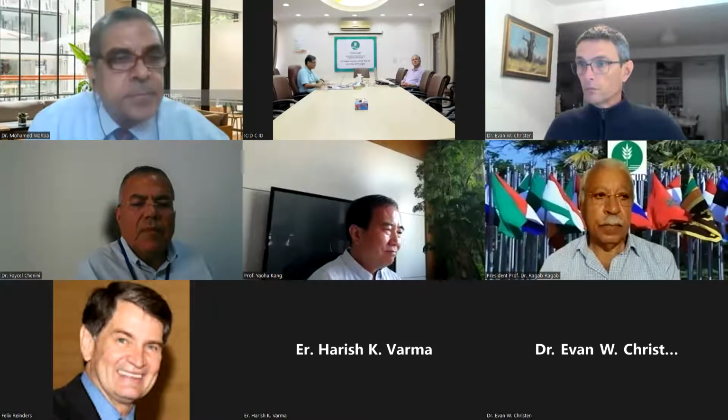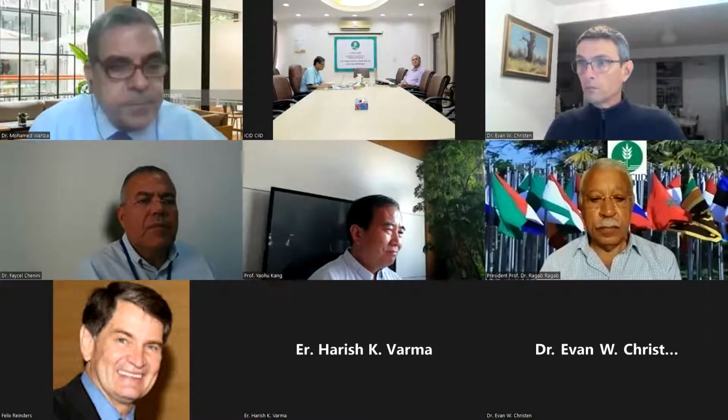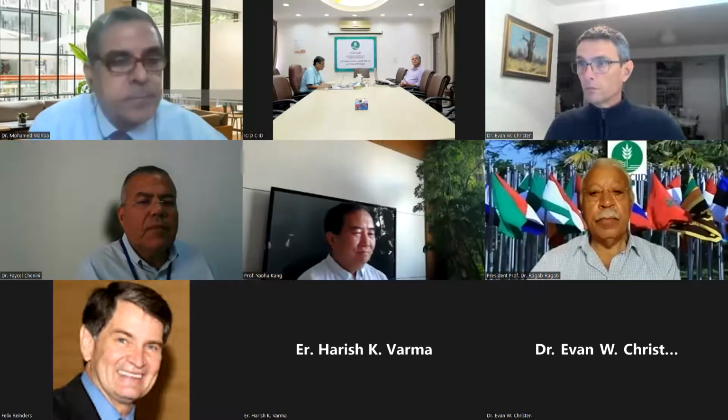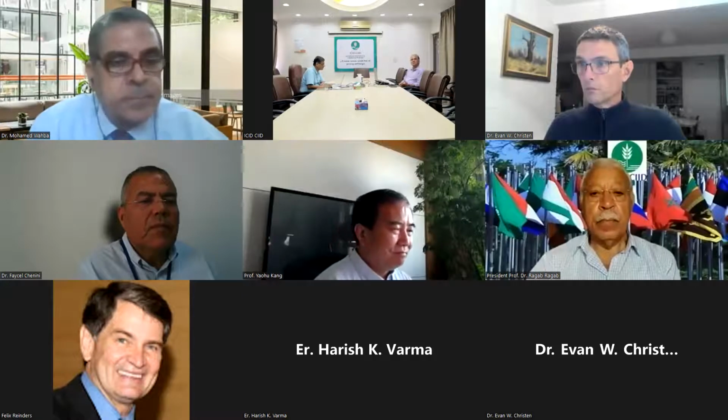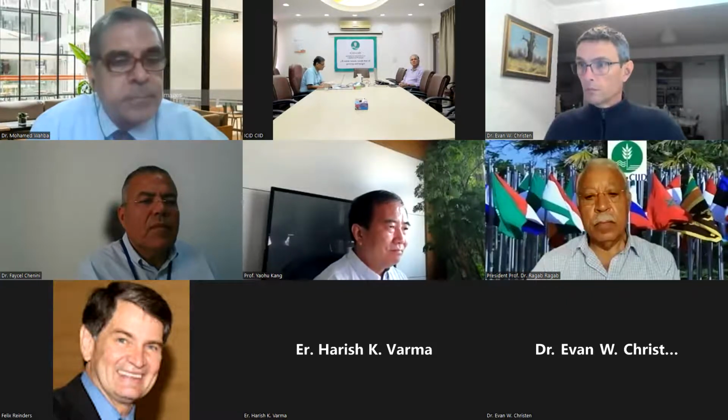But just for interest, we have developed right here in South Africa a uniquely innovative CV measuring cup. It works electronically, so you go out in the field and instantaneously you can determine the variation of the irrigation system, and it will provide you with the liters per hour per dripper, as well as the average and the CV.